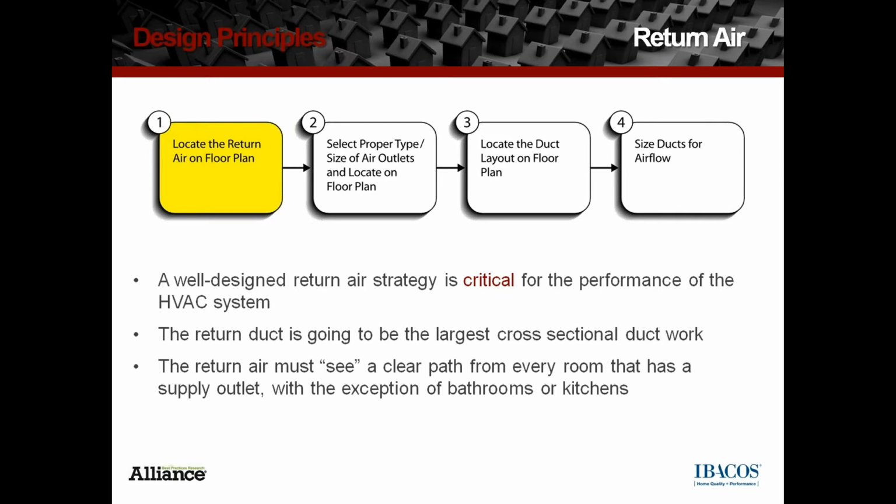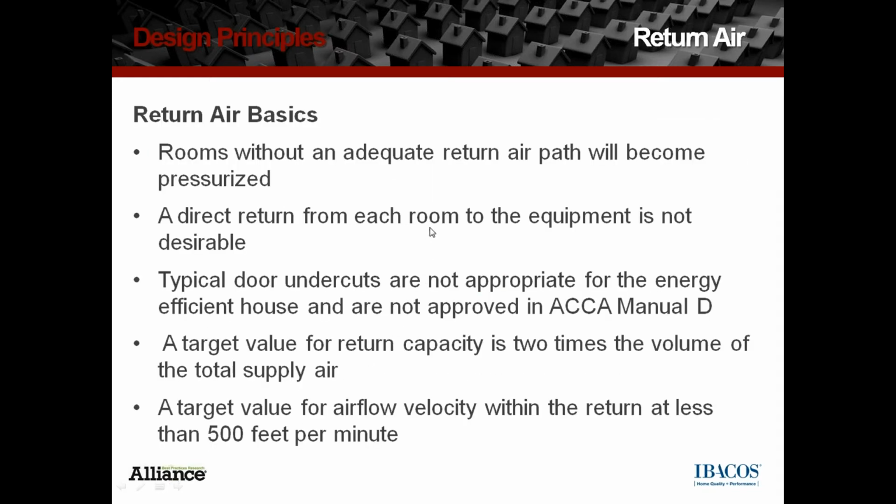Why are you saying we need to locate return ducts on the floor plan first before supply ducts? Mainly for that reason, that its location is critical for its performance, and its size really impacts. You could be looking at 14, 16, 18-inch, 20-inch diameter ductwork for that return.